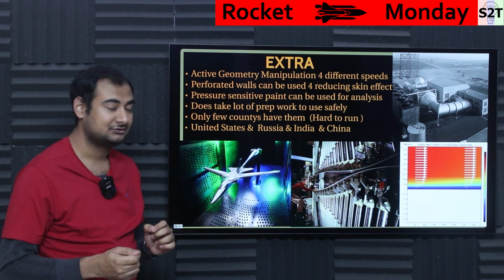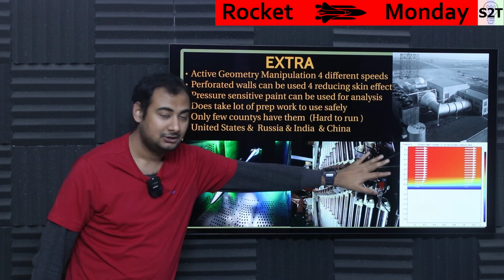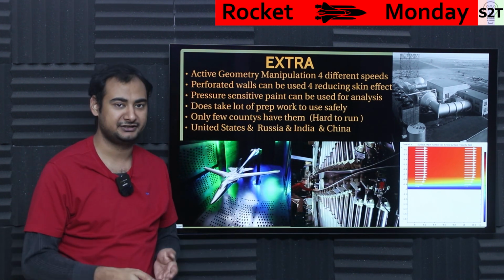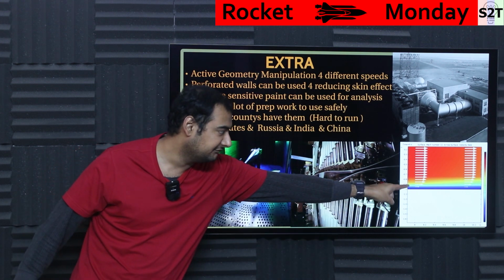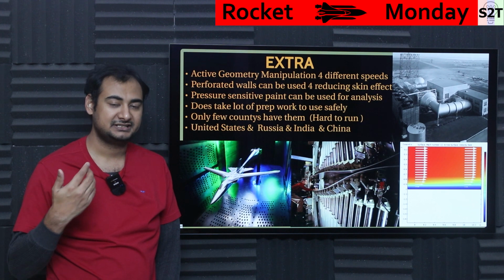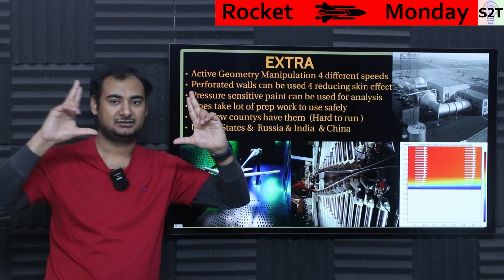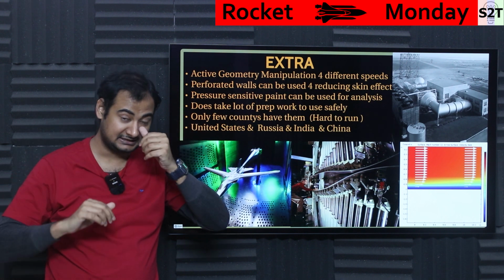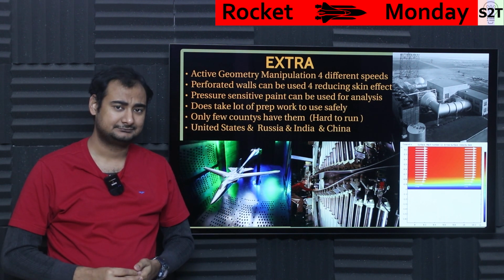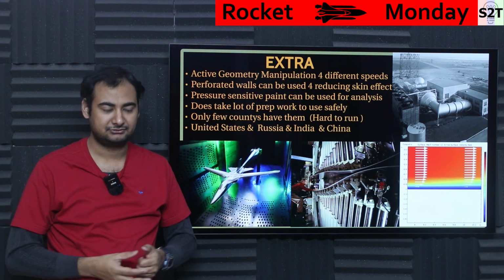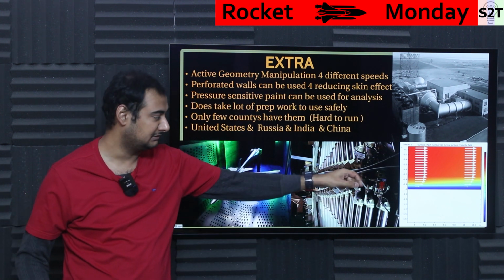At that point in time, you have to deal with what we call boundary layer, meaning no matter how fast your flow is, no matter what you do, you can go Mach 20 or Mach 500, does not matter. You're always going to have a layer of air that is acting like an insulator. Now it's also insulating against speed, meaning if you make a tunnel that is, let's say, 10 square meter, and you're like, how much of an area am I getting that is laminar flow? The answer would be very low, because again, boundary layer will create basically a blanket around. So you have to deplete this blanket layer.